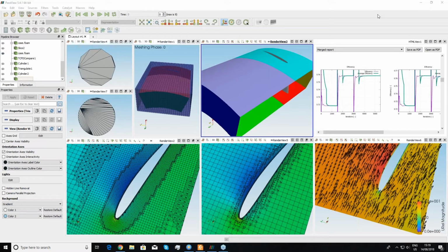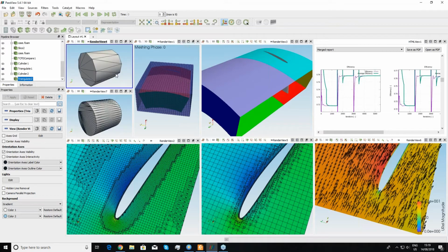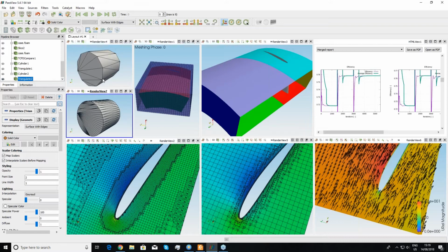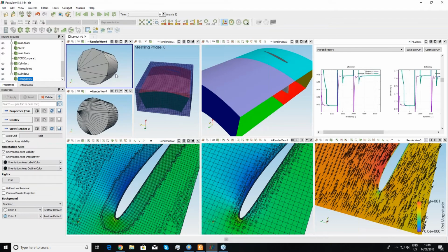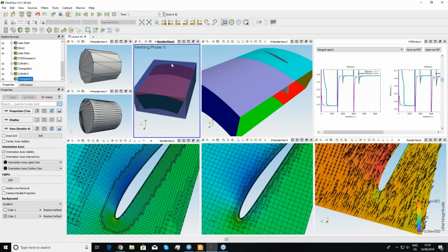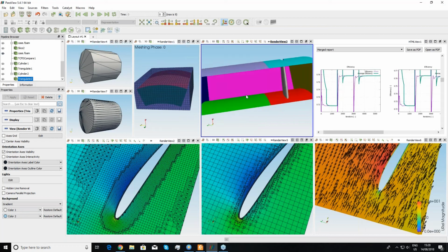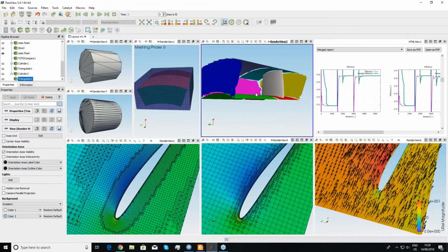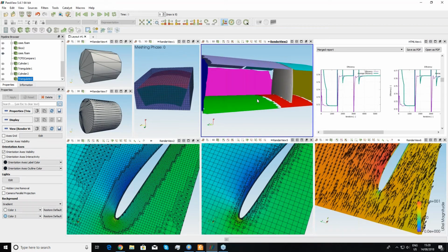So what I would like to show you today is mainly concerning the input geometry, concerning the input STL files which are required for the internal meshing tool, which is called SnappyHexMesh. So I will stay for a while at the input geometry in general, how it should look like, what are the general necessities, let's say, for the input geometry. Then, because we will use SnappyHexMesh, I would like to roughly say what are the principles of this meshing tool. Then we will set up the case, a simple case for such a simple geometry of an axial fan.